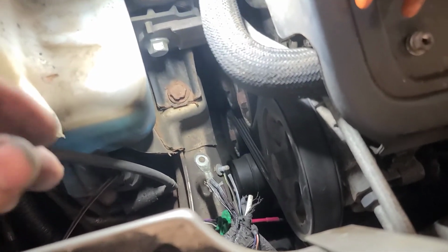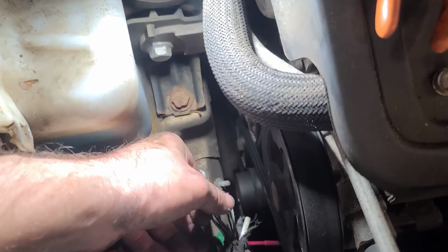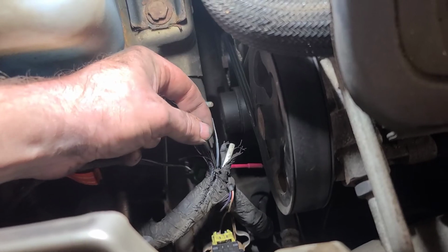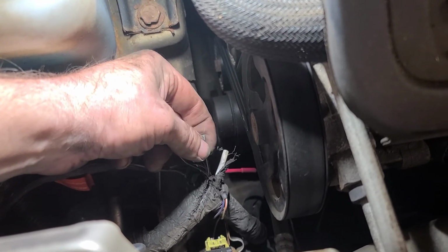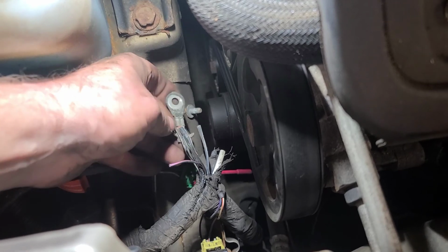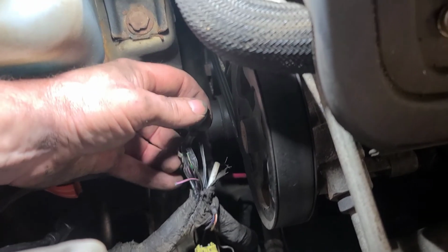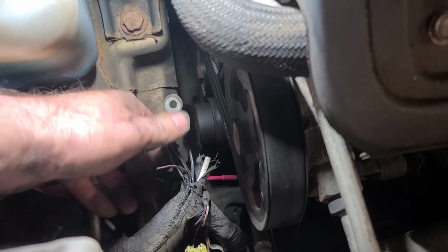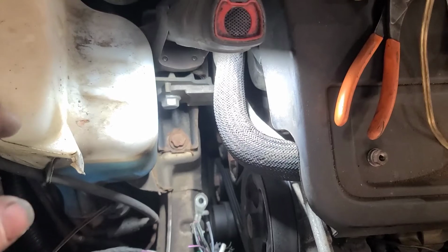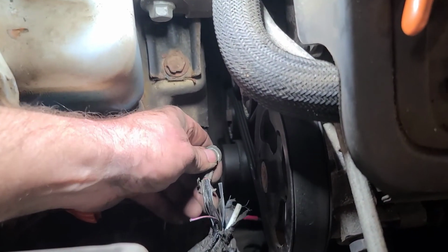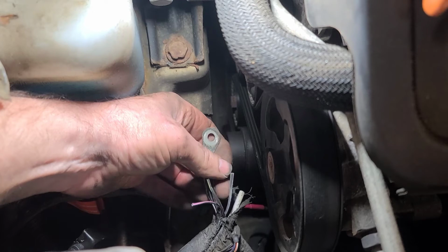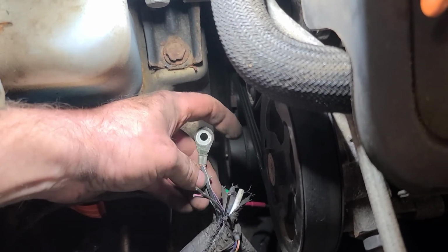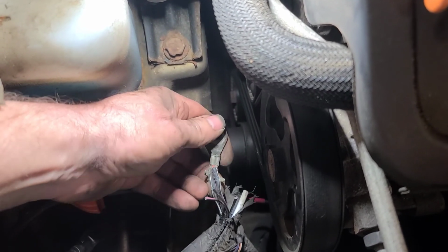So I got that ground out, disconnected it, and you can see the black pink wire fell off, this black yellow wire fell off, and the black white wire fell off, and the rest of them aren't far behind because they're all crimped under this one eyelet here. And I took the overflow coolant reservoir bottle out to give myself some more room, so I'm going to extend these wires, each individual wire, because this is very difficult to fix in here and it'll be too short.